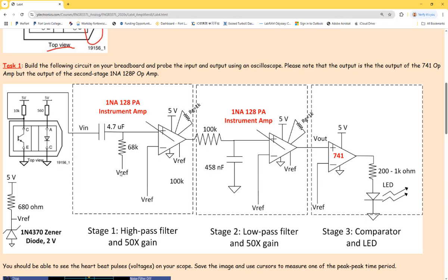So in circuit 1, you guys learned amplifiers, right? Op-amps. But you used the dual supplies, 15 and negative 15 volts. But in the real world, we usually don't have negative 15 volts. It's just trying to let your reference voltage be 0 volts, because you have a bottom and top rail, and in the middle is directly just 0 volts.